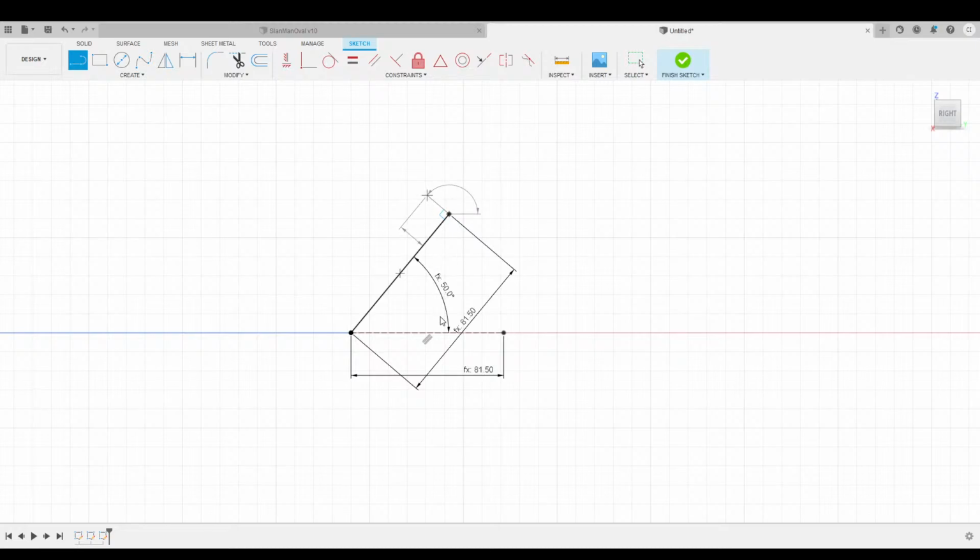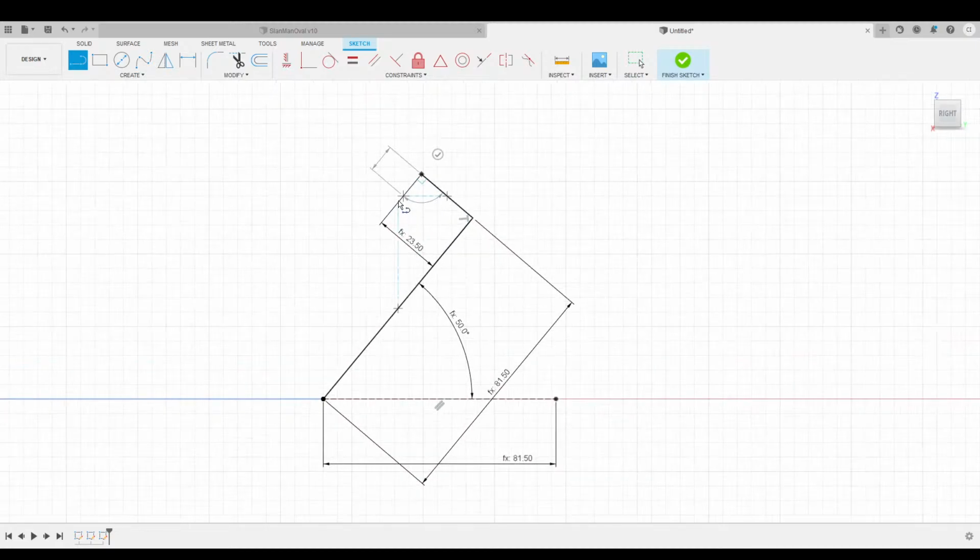Track outside. So one of the reasons, well, it's kind of obvious with Hot Wheels track, is that you want the same dimension the whole way through. So we're just making sure that this whole thing, oh, it's track height actually, is going to be as uniform as possible, because some of the tools in Fusion behave best when everything is exactly the same. And you'll still see it mess up. I'm almost 100% sure it's going to mess up on trying to fill in the body for us here. And then you'll get to see how to try to fix that.